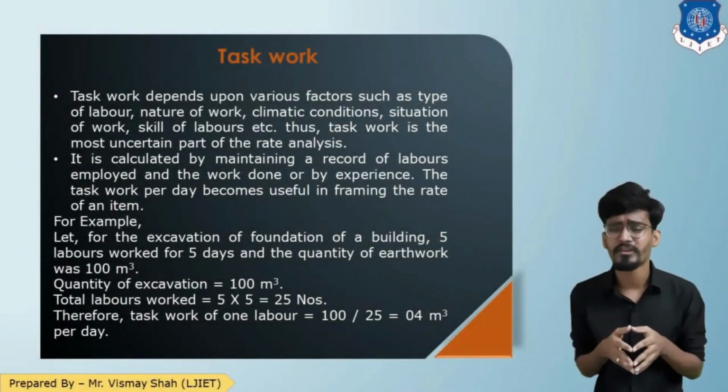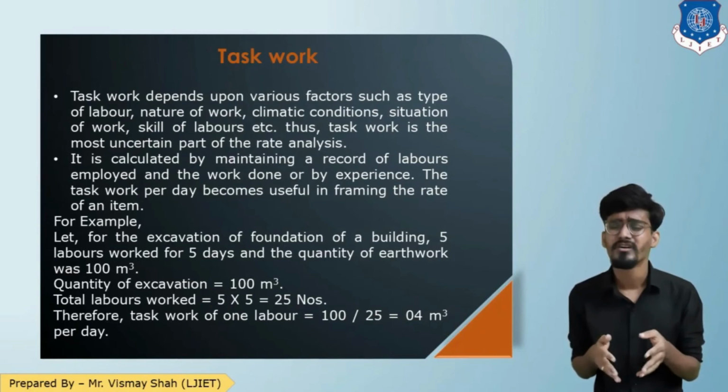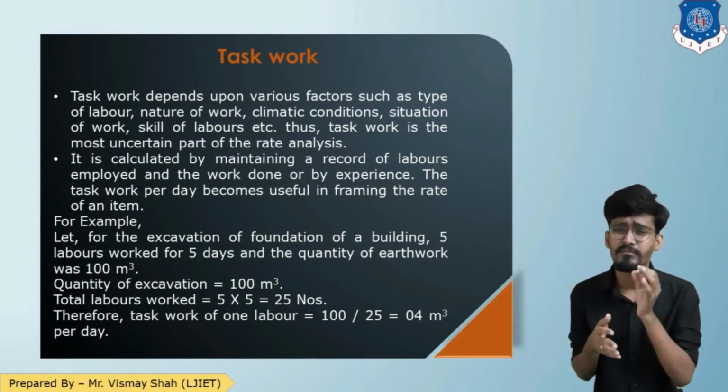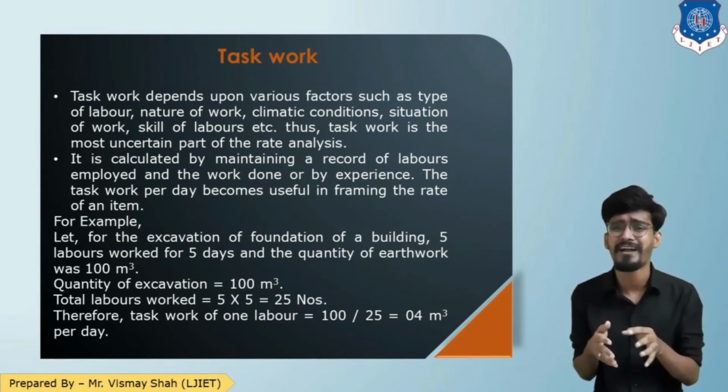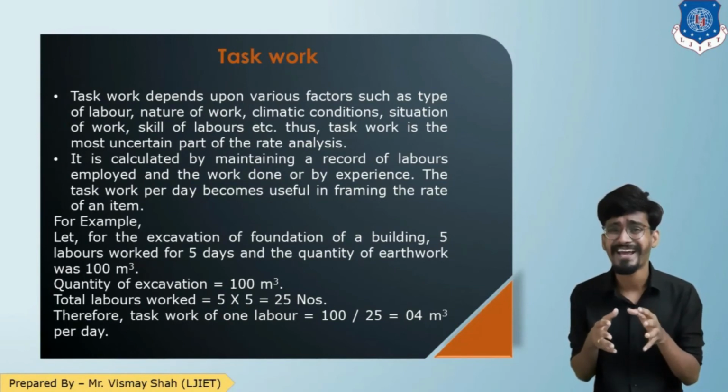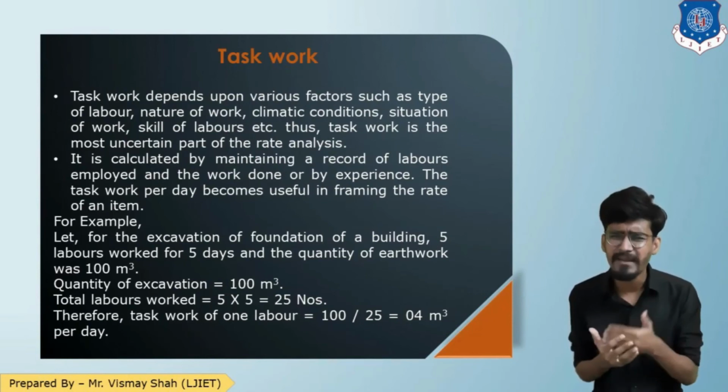Moving forward, the task work depends upon various factors such as type of labor, nature of work, skill of labor, climatic conditions, situation of work, etc. So the task work is the most uncertain part of the rate analysis, because it completely varies from project to project.